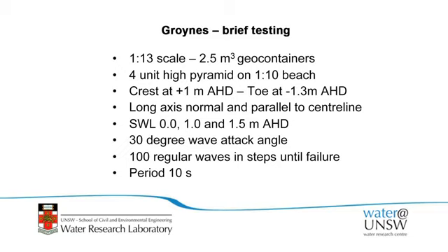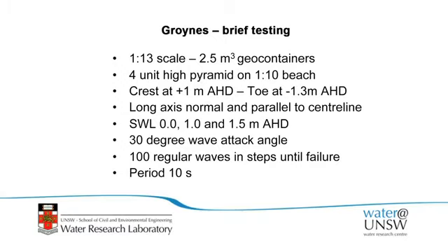Part of the reason for this was a question: are you better to point the bags out to sea for the groin, or are you better to put the bags across the groin? Some of that's dependent on how you want to build it as well. We used 3 water levels: 0, 1 and 1.5 metre AHD. Also realising groins go out into the surf zone, the full wave setup doesn't happen until you're at the shore. So once your groin is out inside the surf zone, you're not getting as much wave setup, so that's still a reasonably high water level once you're out into the surf zone.